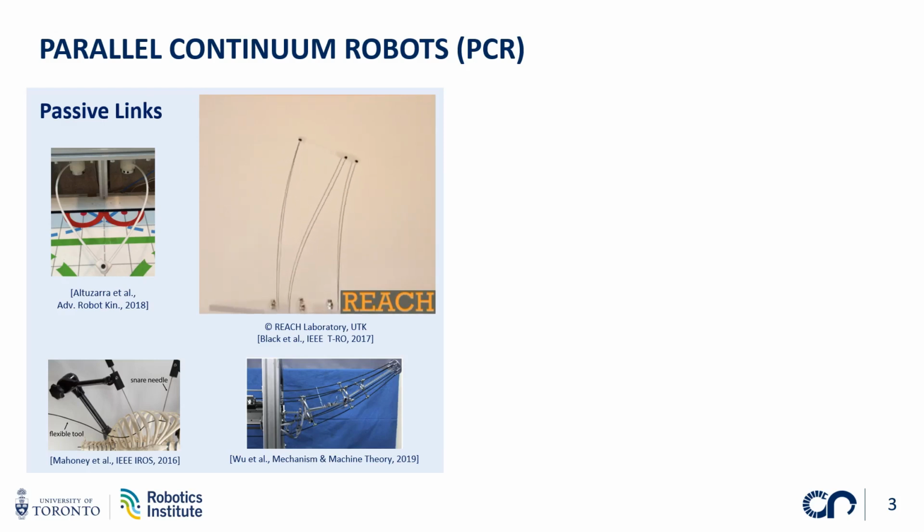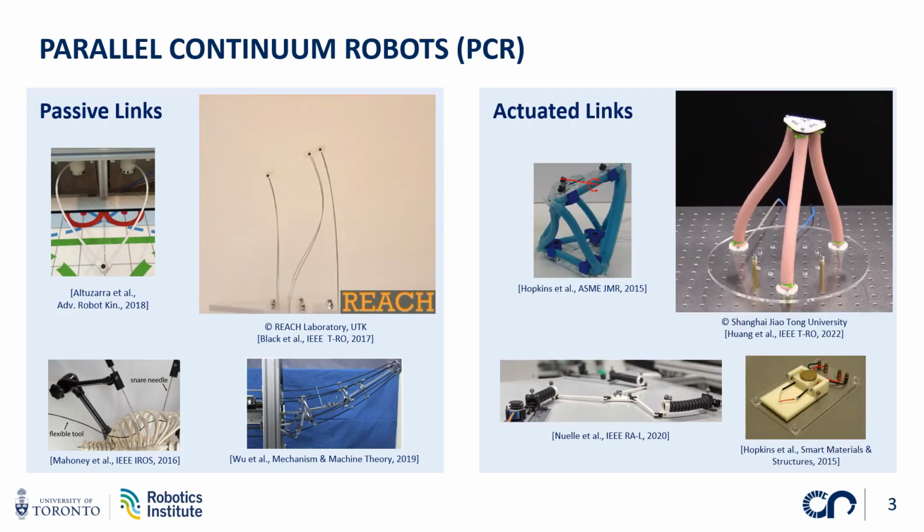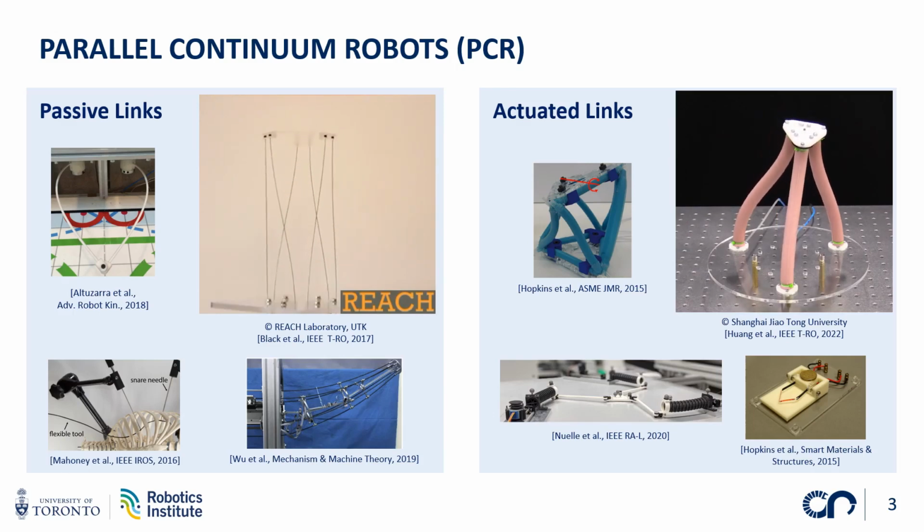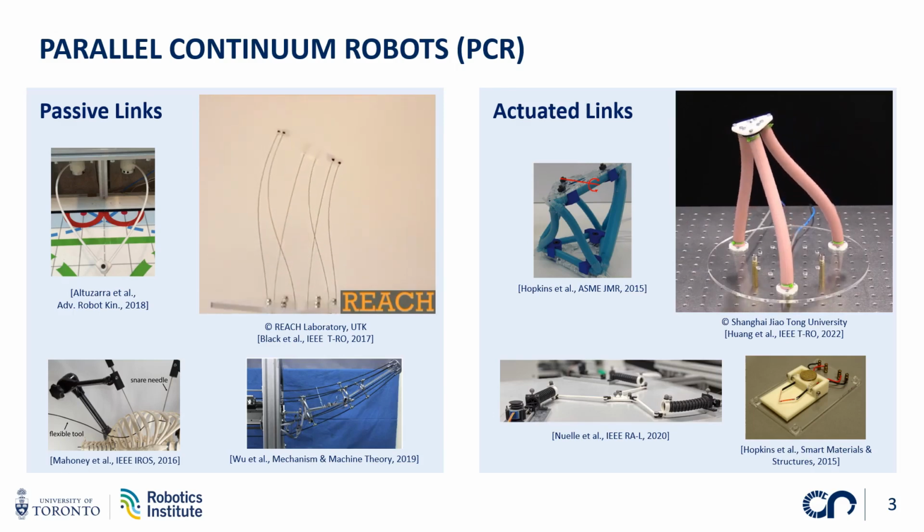One common design approach sees multiple coupled continuum links in parallel assemblies, which are actuated by displacing their proximal ends, while deformations occur passively due to coupling and external forces. Other PCR designs utilize additional actuation principles to actively bend or elongate the shape of each continuum link, leading to additional controlled deformations. Here, commonly used actuation principles mainly include pneumatics, hydraulics, shape memory alloys, and tendons.